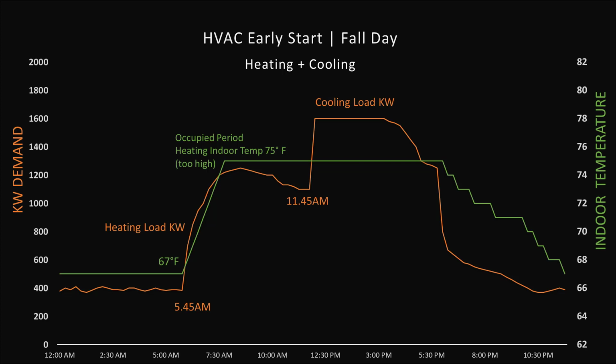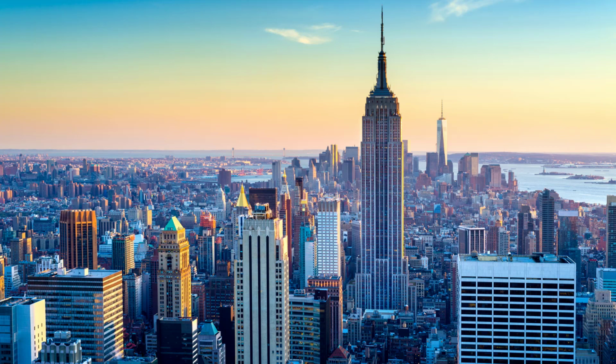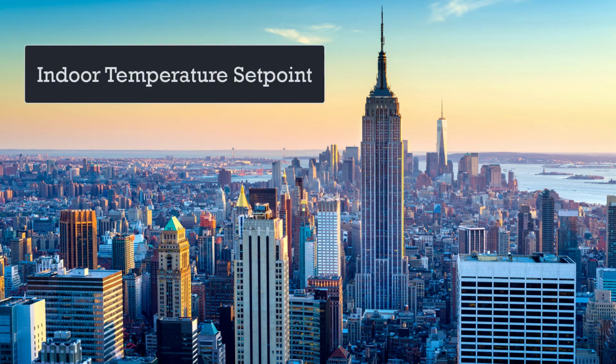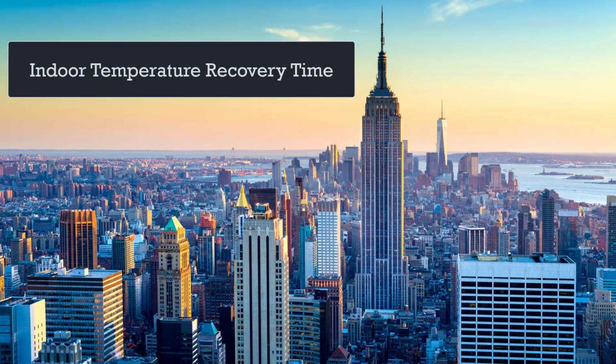If pre-occupancy heating was delayed and indoor temperatures were set at the lower end of the comfort zone, the building would have reduced both heating and cooling energy. In summary, a building's HVAC Optimum Start program should emphasize 3 basic criteria: desired indoor temperature set point when cooling and when heating. They should be different values for each operation. The building's occupied period begin time, otherwise defined in the landlord-tenant lease as the time HVAC service begins during weekday business hours, and building indoor temperature recovery time, verified by monitoring indoor temperatures prior to and at the occupied period begin time.